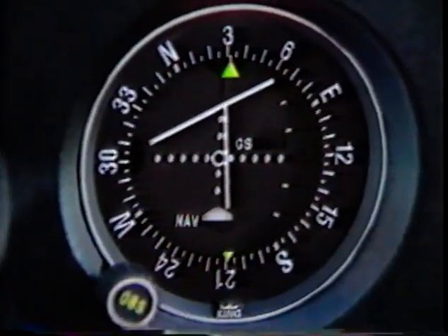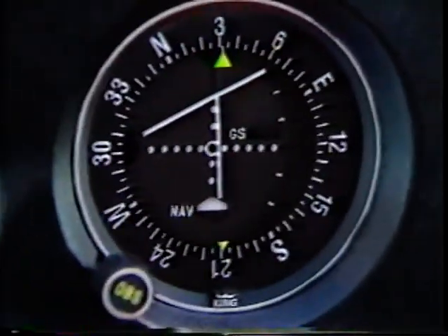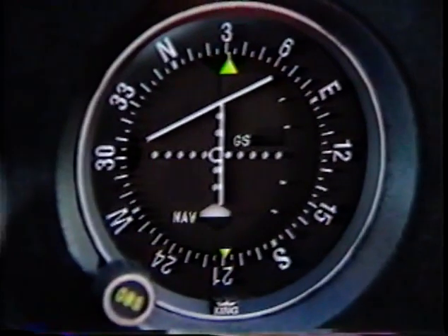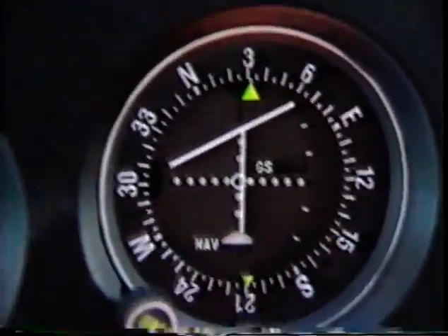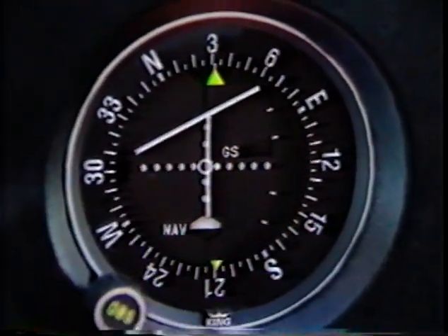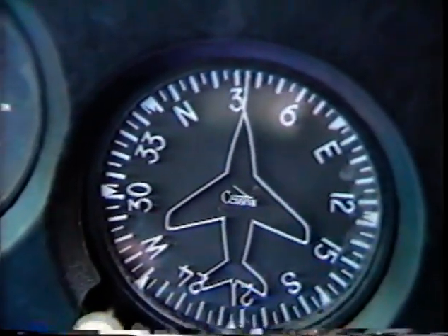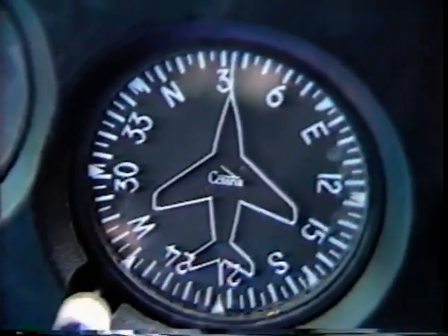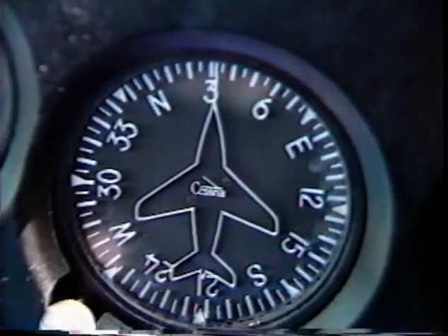As long as the CDI is stationary, you are a constant number of degrees off course. Since the localizer narrows toward the runway, you are actually getting closer to its center line. The important step at this point is to note the DG and mentally record the reference heading.